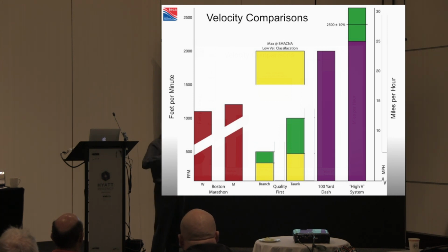A trunk duct can have a little bit higher speed than a branch duct for 2 reasons. A big duct is aerodynamically more efficient than a small duct. It has more square inches for its wetted surface area, all that kind of thing. But in the branch duct, you can't get those speeds because you're right under Mrs. Smith's nose and right underneath her ears, so we have speed limits on the branch duct that's 5 miles an hour. You cannot exceed these speed limits, but they're being exceeded all the time.